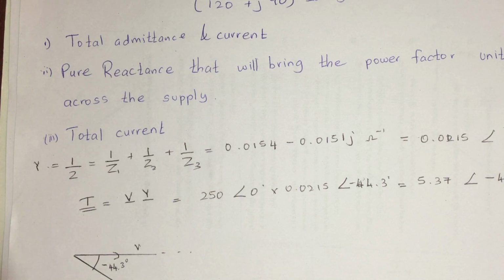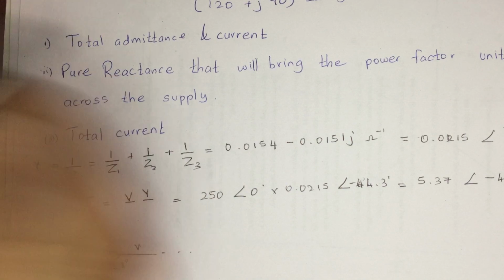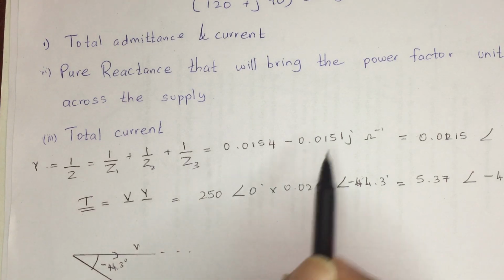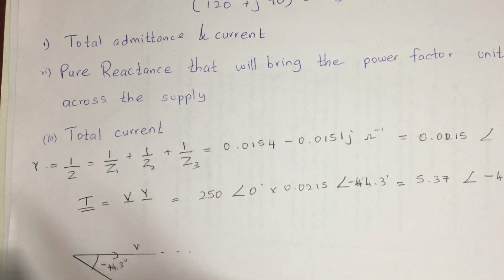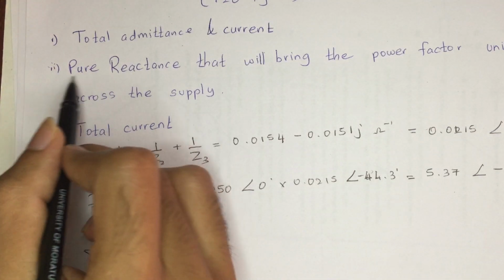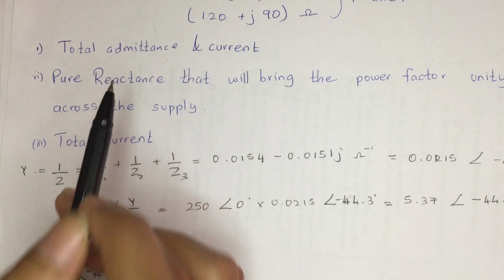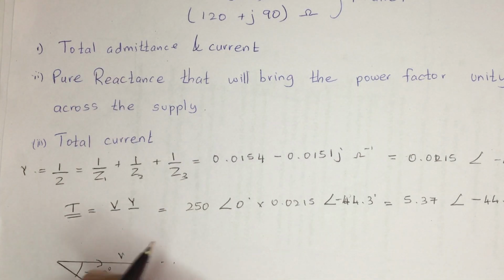In this question, we can't change the voltage; for that instrument, we are going to supply the same voltage. As you can see over here, the voltage is leading, so it's an inductive circuit. So we are going to add a pure capacitor, because when considering a pure reactance, we can't add an inductor. If we add another inductor, the inductive nature of this circuit is going to increase. So we can add the capacitor in parallel.